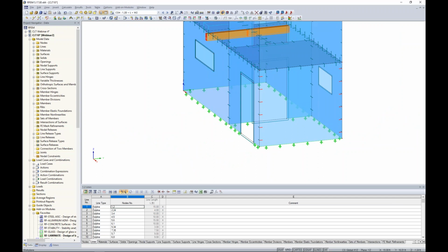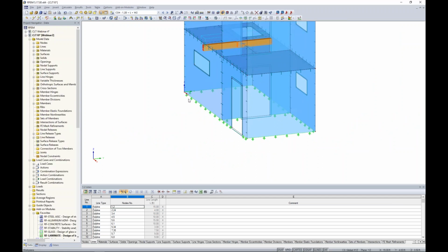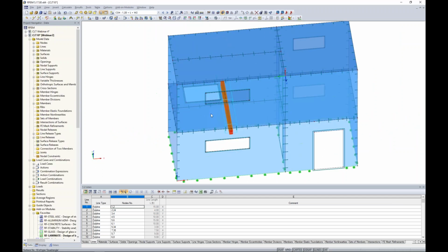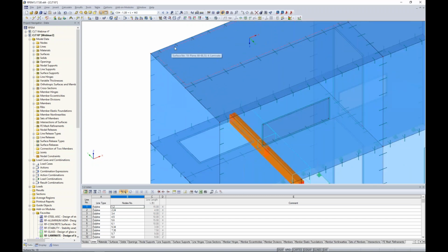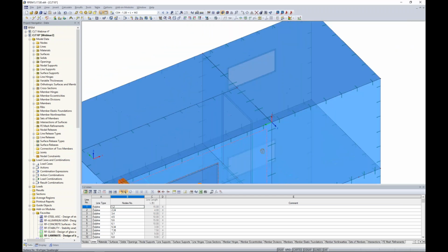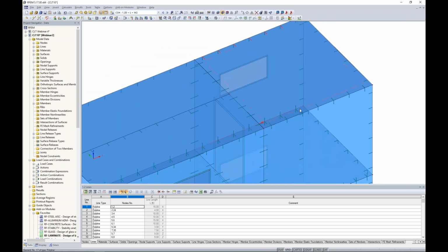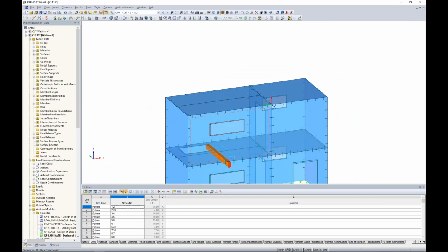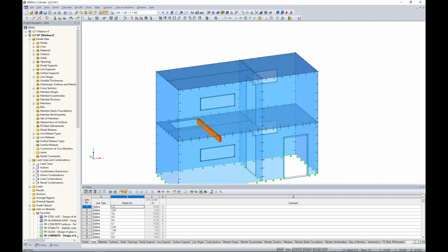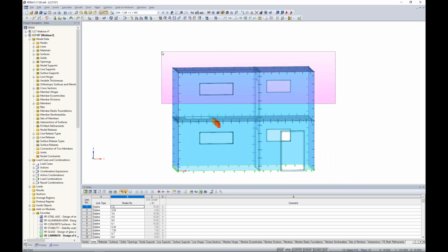We select some of these locations where we have too many line hinges defined, and up at the top, same thing. Otherwise, we want to avoid those instabilities. So holding down my control key, I'm just deleting some of them, and finally over here on the right hand side. So that takes care of the roof element, but we also want to select our second level here.